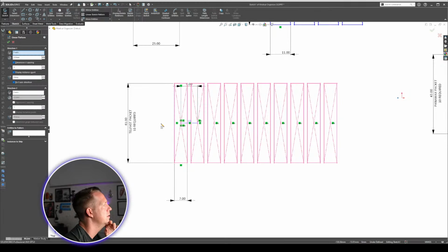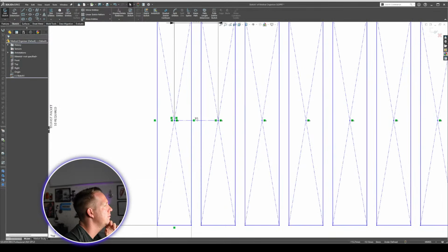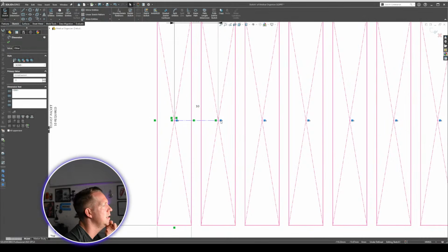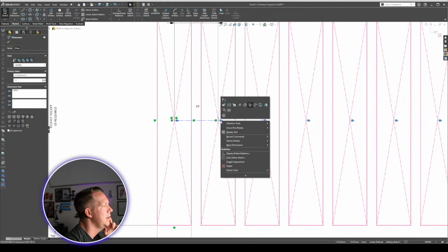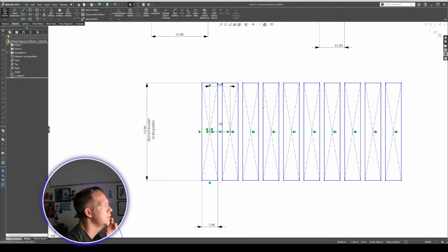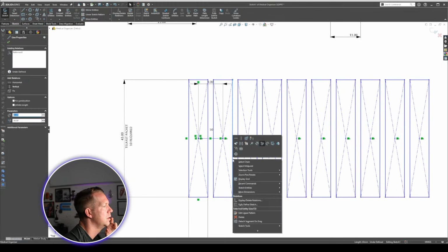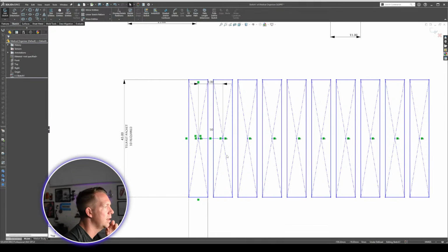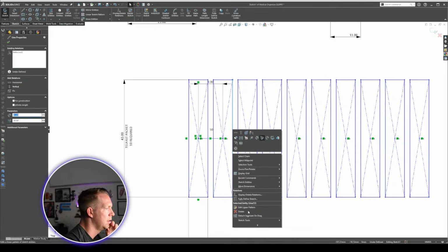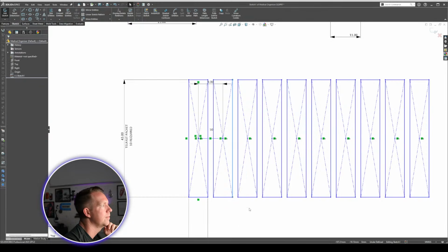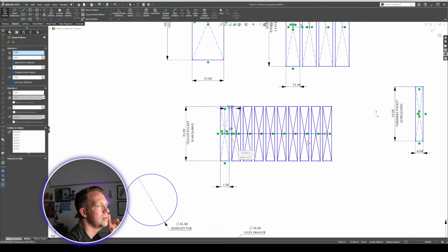I think that's going to create a new one. Yeah, we'll have to find it. I've seen the tip recently. It's not something I use very regularly, but it's definitely possible to do. Edit linear pattern. There we go. So I selected one of the elements from the pattern, and I get the edit linear pattern option, and then I can come back and change the numbers. So that's how we can get back in and change not only the numbers, but whether there's a y-axis pattern as well.